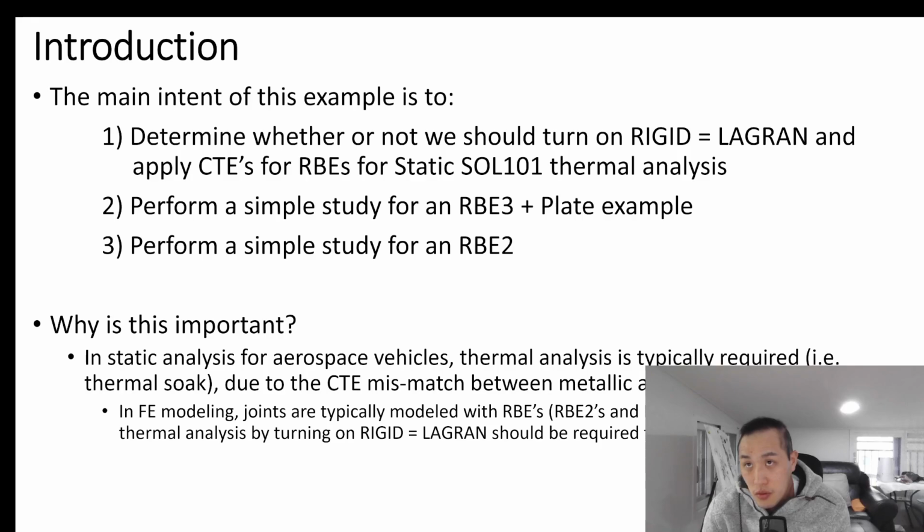whenever we do modeling, we obviously use finite element models, and in medium density models, we typically model all the fasteners or most of the fasteners as much as we can at the joints, and typically for elements with dissimilar meshes, we will model them with RBE3s, CBUSHes, and RBE3s, a combination of all those. And then also sometimes people model RBE2s in their FEMs in various ways.